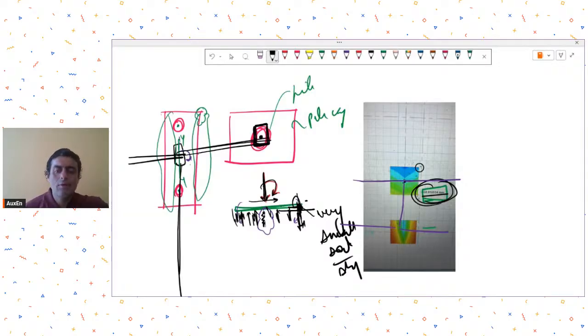So if at these corners or at some points you are getting very large deflections, I would say take an engineering judgment and ignore it, but please ensure and check why that deflection is coming. And as I told you, if it is just because of the configurational issues, it's okay to ignore. So these things: assign soil stiffness below your pile cap also.